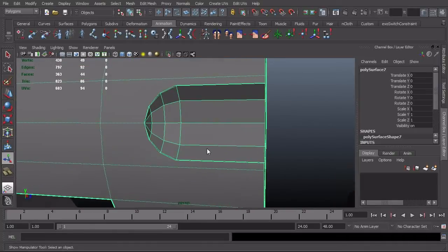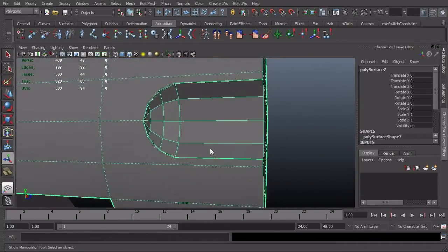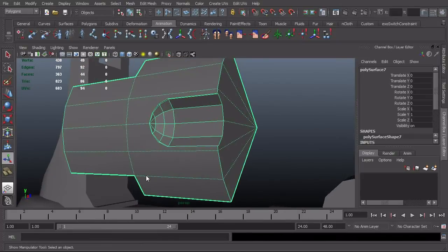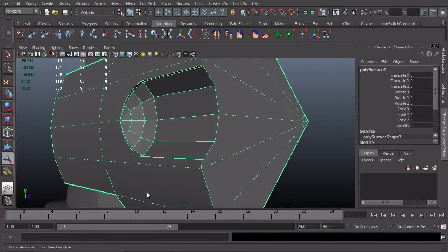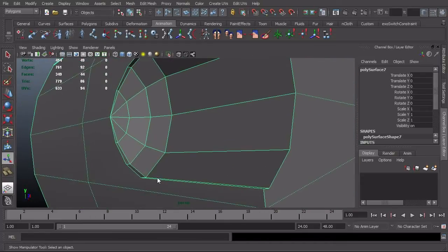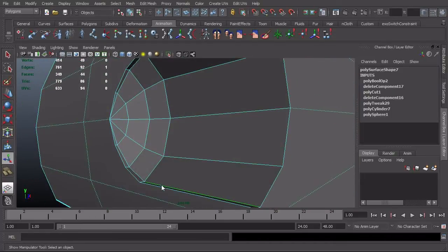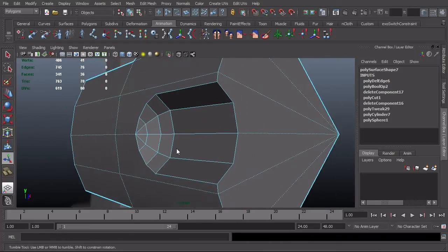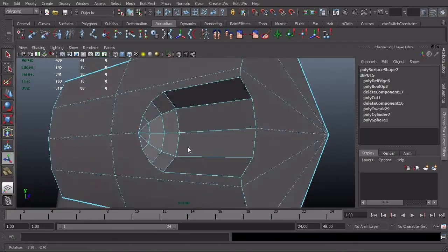This is something to be aware of when you're doing Boolean operations. Every single time, almost, maybe not every single time, but nearly every time you do a Boolean, you're going to have to clean it up. So this is the span right here that I felt like maybe we didn't even need this span at all. So I'm going to first just try deleting that. See, that still holds up fine. Definitely don't need that span.